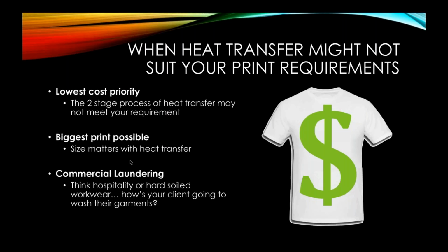Commercial laundering. Now, think hospitality or hard soiled workwear. Definitely hot washing transfers: we print them with heat, so that's how we get the glue to bond with a garment. If they're being hot washed, if they're being dried in dryers, commercial dryers in particular, that heat is being added to the print again, but you don't have the solid pressure down onto the garment.